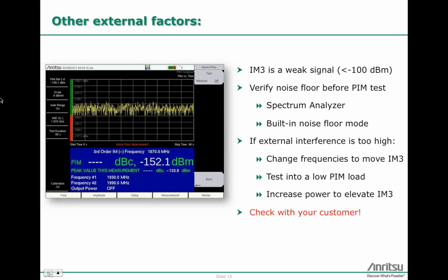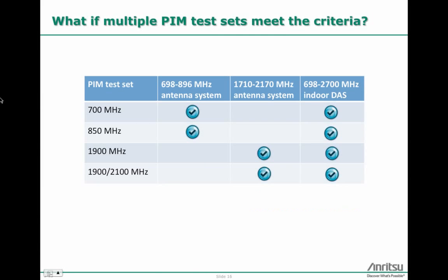This allows you to certify the construction of the site, but it does not allow you to look at the antenna radiation or things external to the antenna. Another option is to increase the power. All of these things, once again, you need to talk to your customer about before you randomly start changing frequencies, bypassing components, transmitting into loads, or changing the transmit power for the site test.